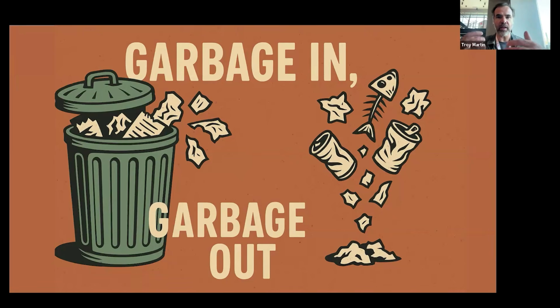I want to make sure I collect it when that door is closed, because that's generally the more difficult or more restricted RF condition, right? Once I've collected that data, I walk back out the door and repeat that process, pausing as I open the door, pausing as I leave the office, and then just rinse and repeat as I move in and out of offices. So directly to answer the question, I'd recommend surveying office environments with the door closed. Now, it does take longer, and you do need to account for that in your time on site so that you can open and close the door.